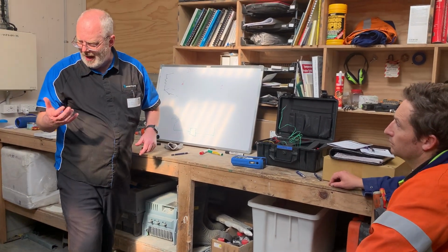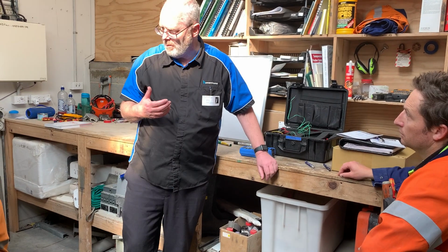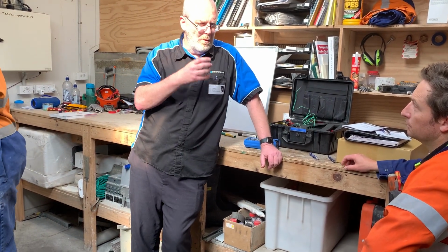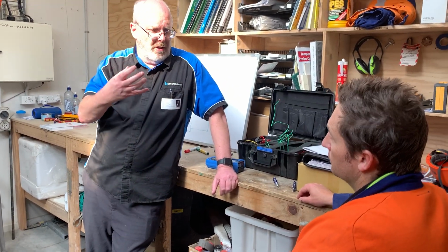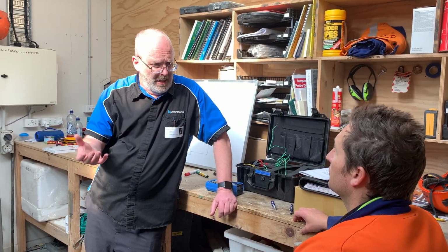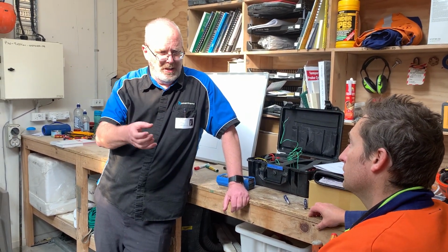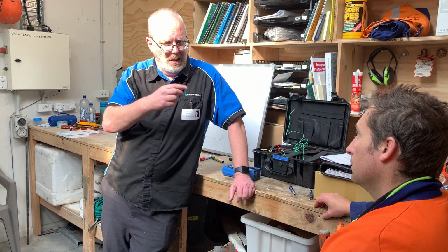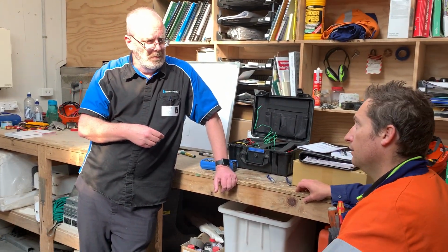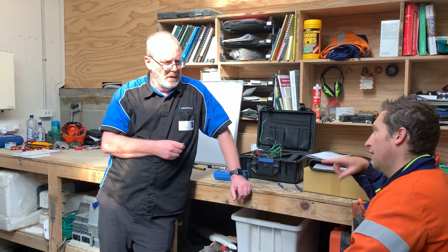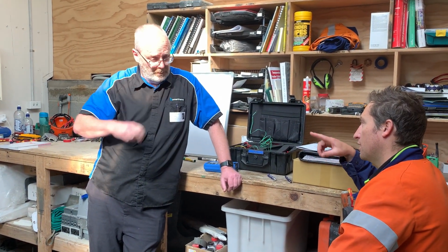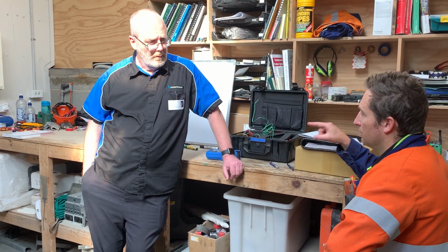Every thermometer you have that has a thermocouple has a cold junction temperature electronic sensor in there, which does take the ambient and adjust for that, but it doesn't affect the reading because you're still just generating a millivolt signal. So don't worry about the ambient. The ambient has no effect. But that K-type temperature that I'm getting off that probe is 100% accurate? Yes.